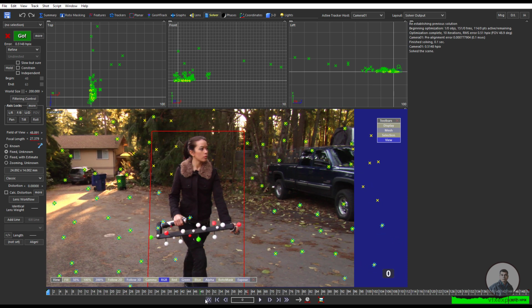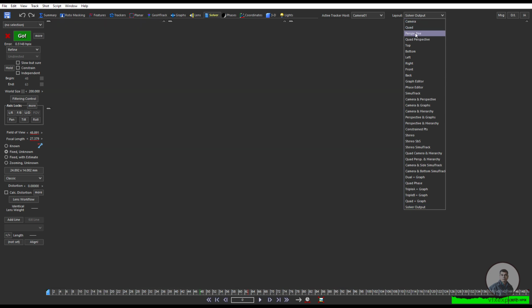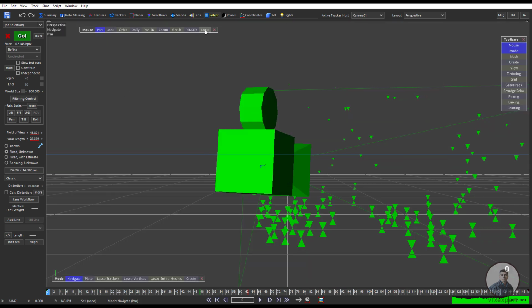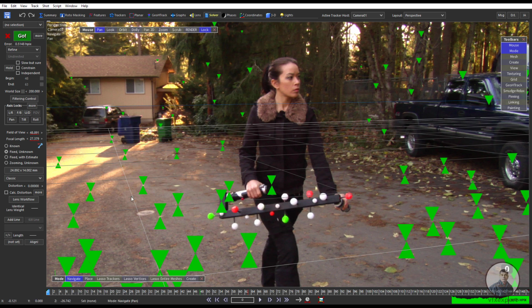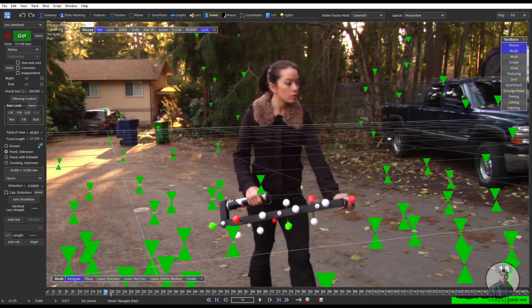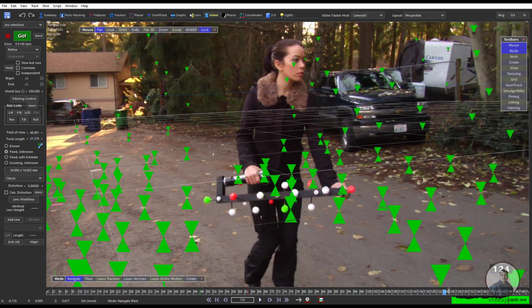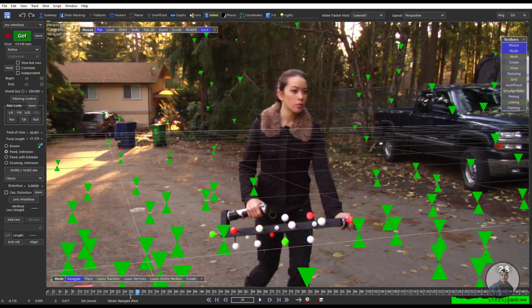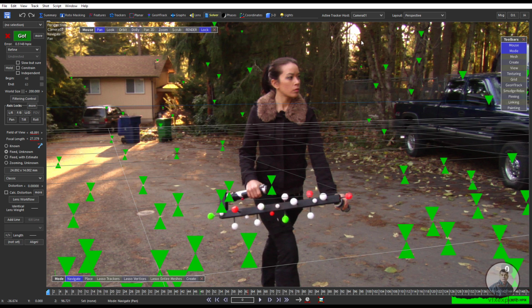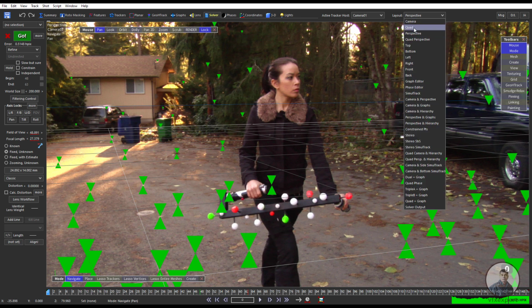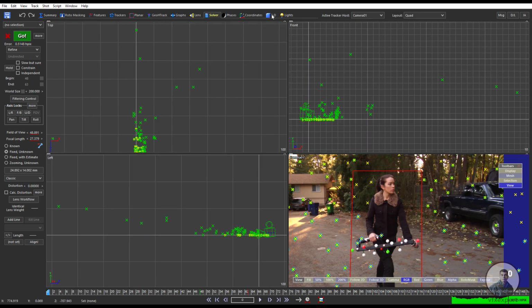Now if you want to check through the perspective view, go to layout and select perspective. Now lock this camera. Now you can see this grid and all these 3D points here. This is our grid, so you can check your perspective. Now again select this quad view, then go to this 3D view. Inside this 3D view, you can create your test geometry according to your requirements.